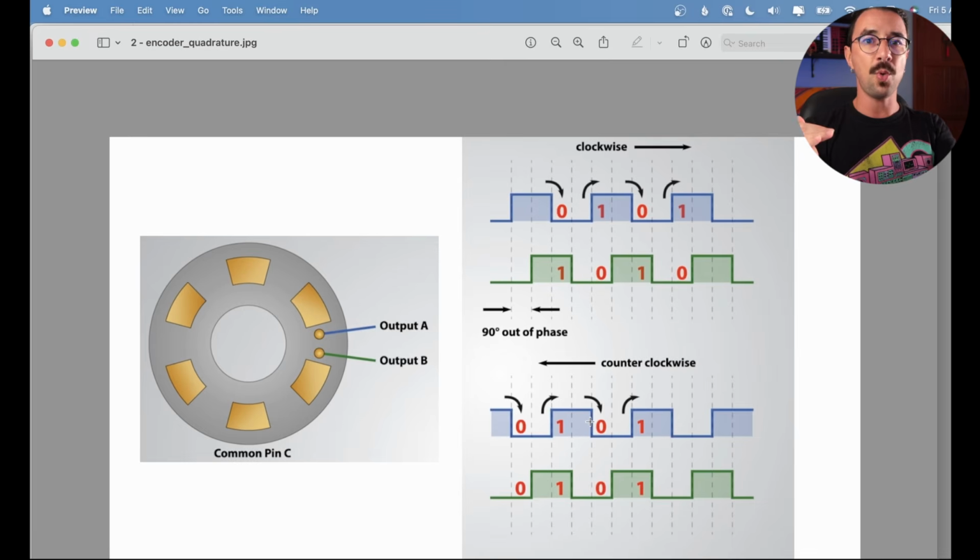So there's the complicated way of writing this code, manually coding all of that. Before I go to the code, there's something really important. Remember that our Arduino code is read line after line in a loop. So imagine that you're turning the rotary encoder knob. Remember that you have 2 terminals. One is going to be on and the other one is going to be off, then off, on. Imagine that when you're reading the code, your code was not fast enough to get that movement, to get that change in the state. And that happens a lot. What will happen is that you will miss pulses.